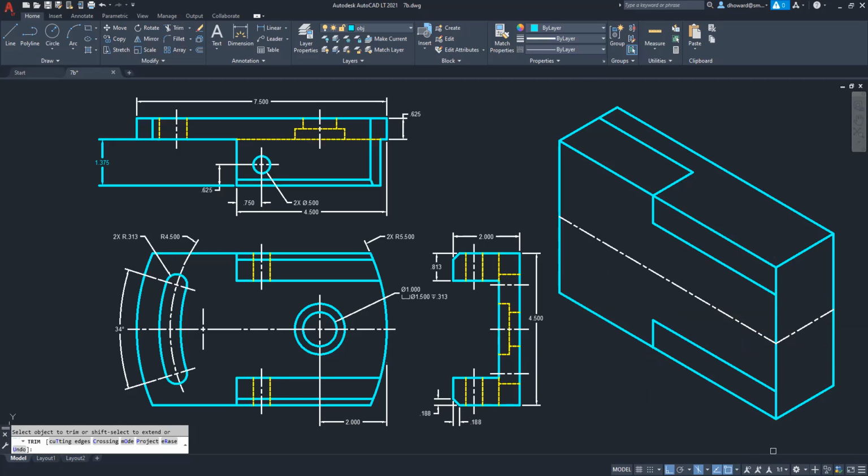So then we go in, right? And how far are we going in? We already talked about that. It's 1.375. So I'm going to go to my line, click on here, and pull in that direction 1.375. There it is. And then we're going to go this way. So this side is, as we already mentioned, 4 1/4, 4.25. And then I'll just close that.